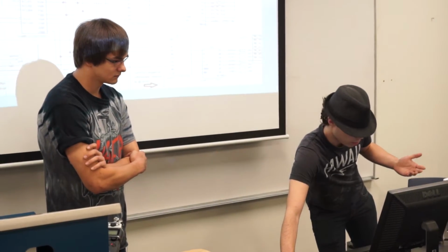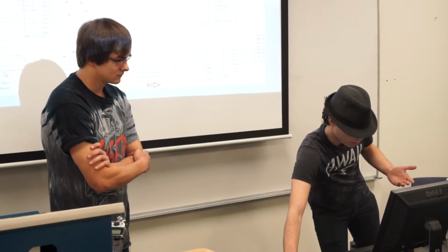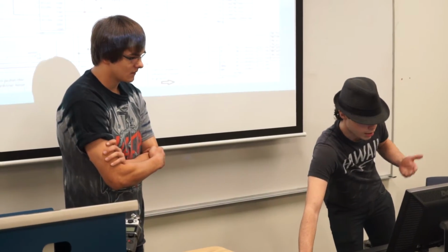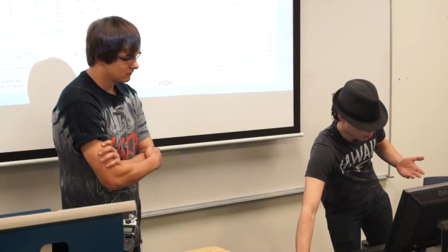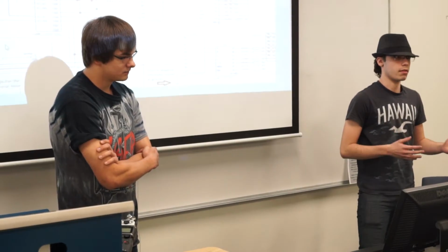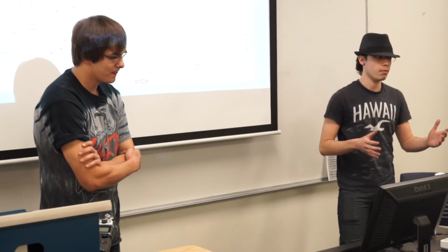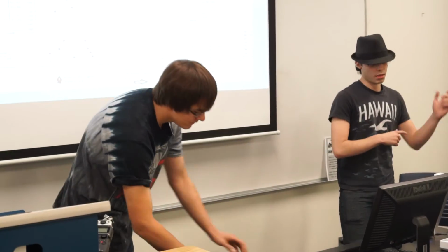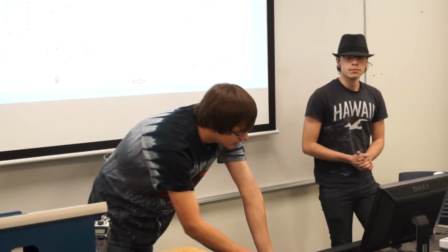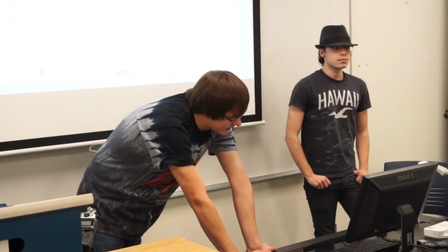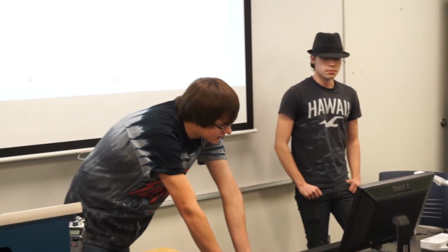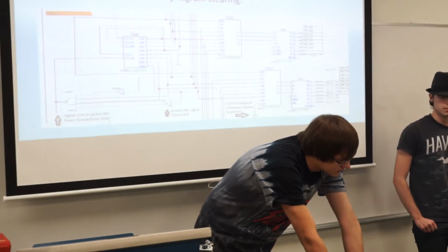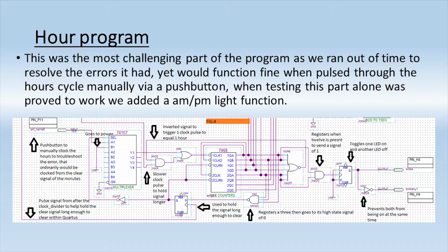It's essentially just the representation of the 60, or 6 anyways, which was the key part: this was a 1 signal inverted to make it 0. These two middle signals were both still 1, and then the last signal was inverted to make it 0 as well, therefore equal to 6. Once all of that was met, it was sent to the NAND to send a clear signal. Now, it should probably be noted that these 4 outputs go to the right 7-segment driver, and then the 2Q outputs go to the left 7-segment driver as most significant and least significant.